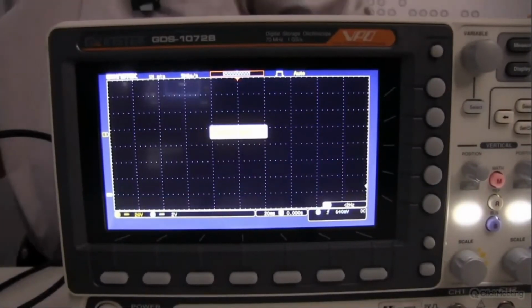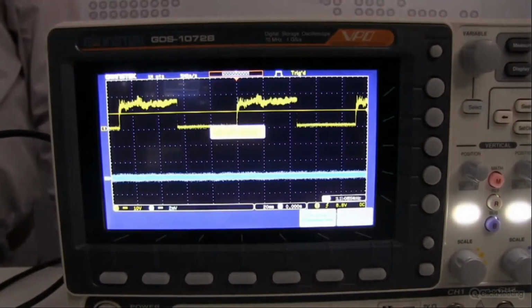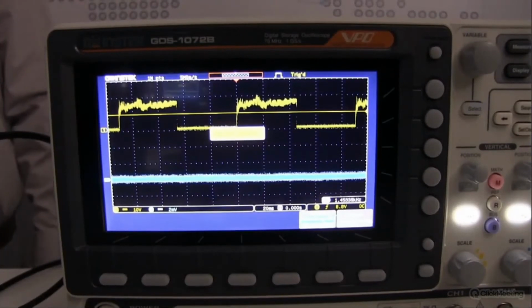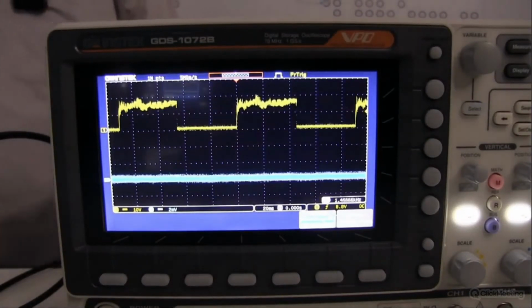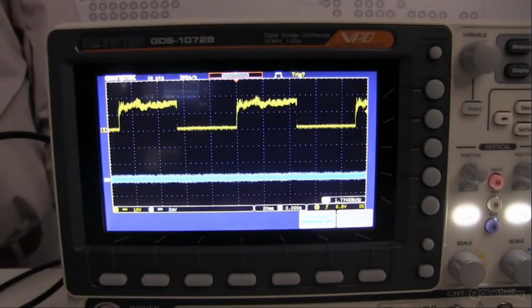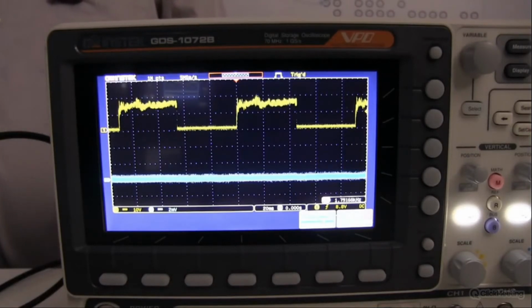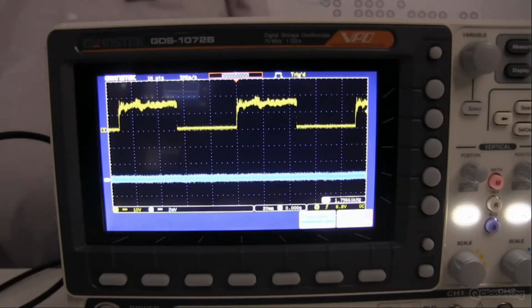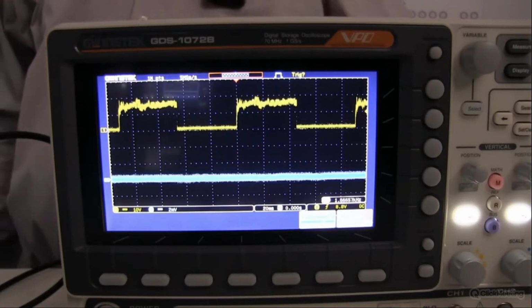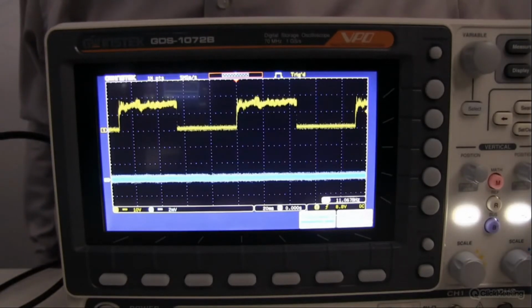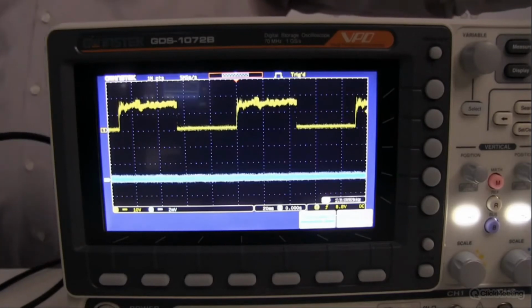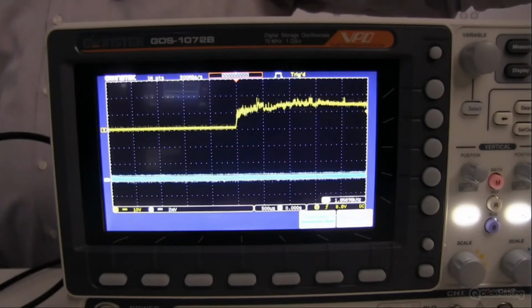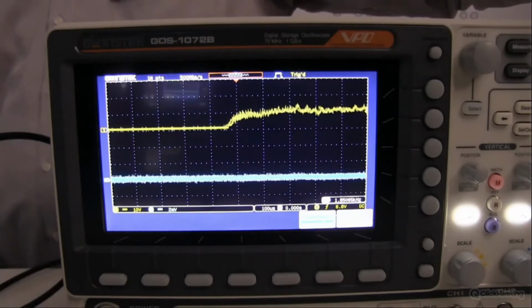And as with any modern oscilloscope, just press auto set and you're done. And I was modulating my pump laser at 11 Hertz, so it's switching on and off in a regular interval, and that's exactly what you can see. It's off when the output is low, and now I can have the oscilloscope zoom in on the very detail.